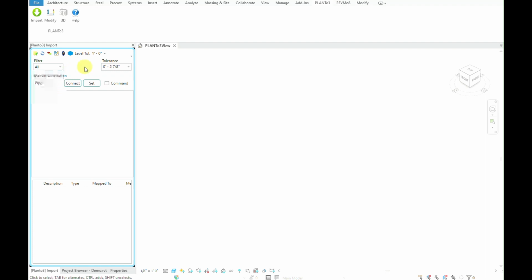The tolerances is the value you set to use when manually connecting pipes with fittings. Manual connection allows you to manually connect pipes with different fittings. Select which fitting type to use, then click Connect. Based on the type you selected, the program will ask you to pick appropriate faces on the pipes to connect.